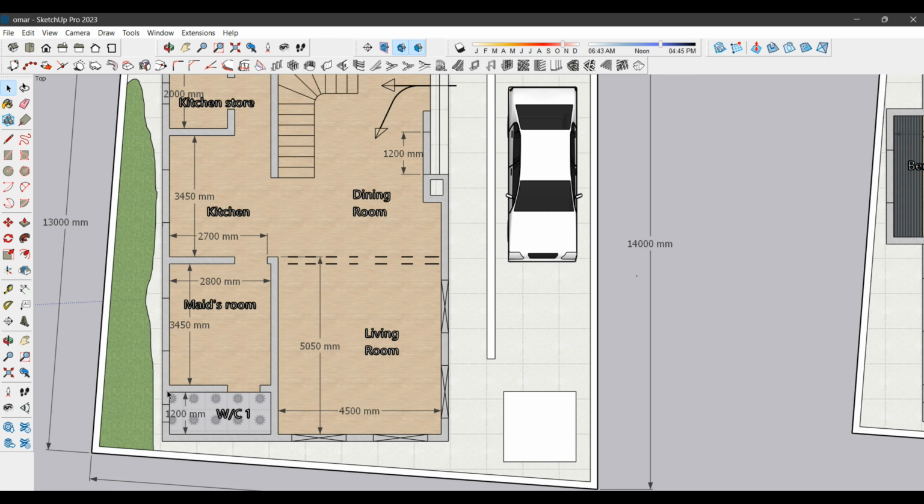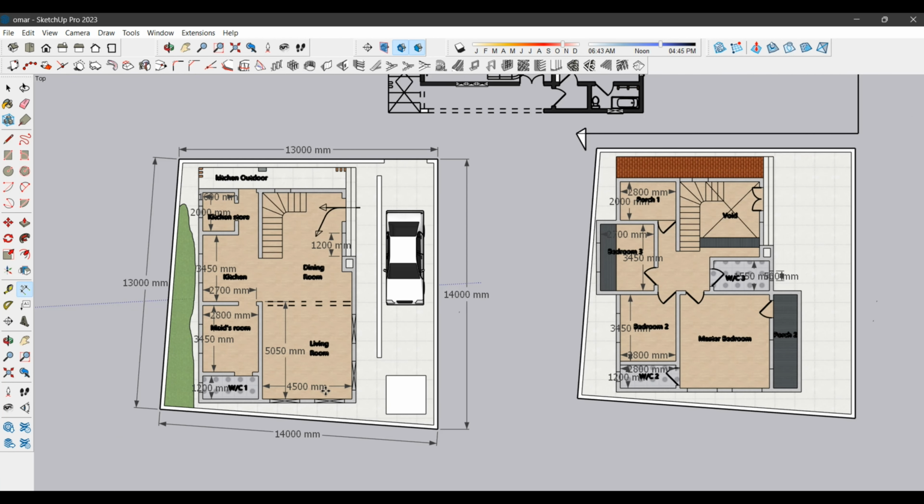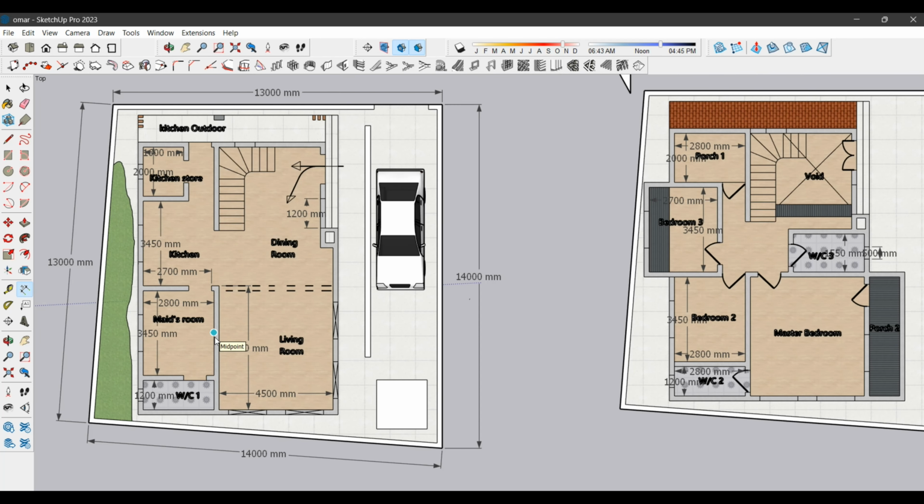5.5. I think I can decide to put a beam here so that I reduce the area of this ceiling here. I can decide to put a beam and then I put the hidden beam somewhere along this area, so that I have a ceiling of 3.4 by 1.2, because I don't want to cover the whole of this 5.5 or 5 meter entirely with slab, and we're also going to be using max span slab.